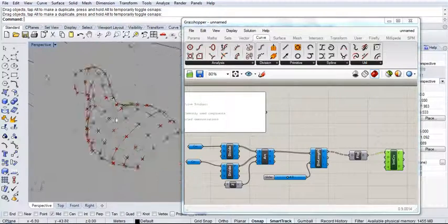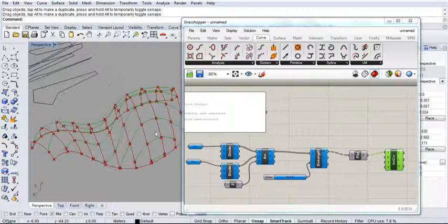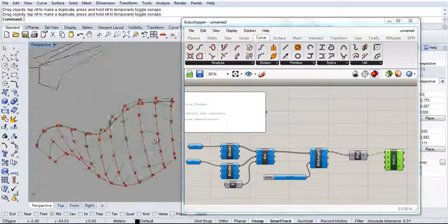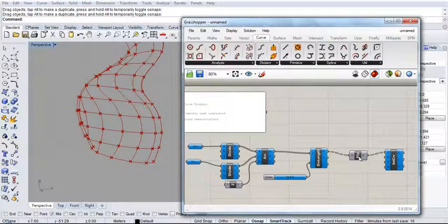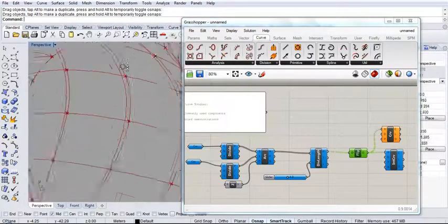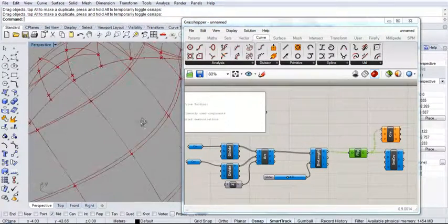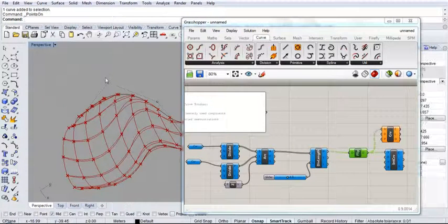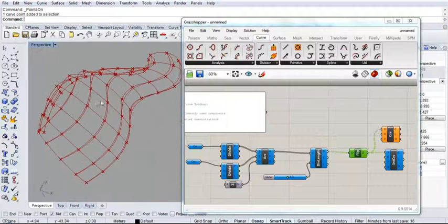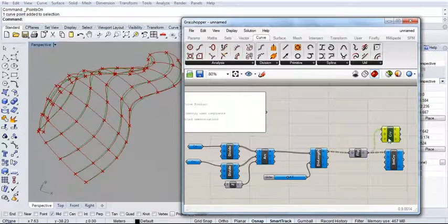So that's really useful for creating grids and wireframes and things like that. Unlike the normal curve component, which uses points as control points. So just like our input curves don't fit exactly through the control points that we specify, it's exactly the same using a curve component or an interpolate curve component.